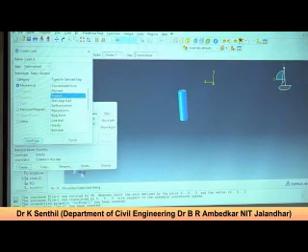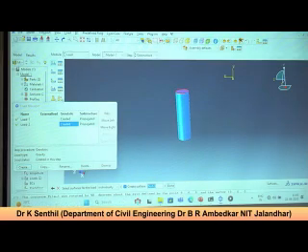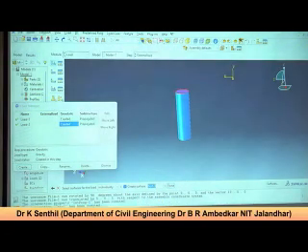Step should be external load. Continue. This is the surface on which it acts. See, you can model the pile cap also. You put a pile cap over this and define the interactions with a sufficient coefficient of friction, and then you put a load. Or if you still want to model a structure, like a 5-story or 10-story, with small panels, you can model it and apply the load as external load. So now this is done.